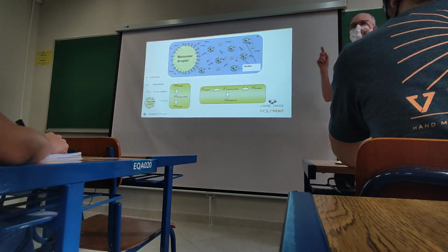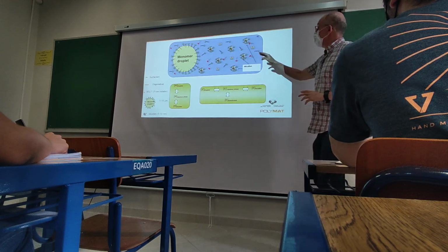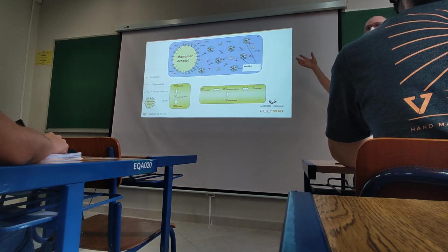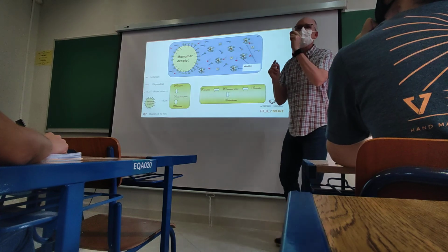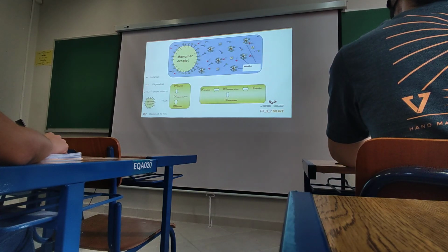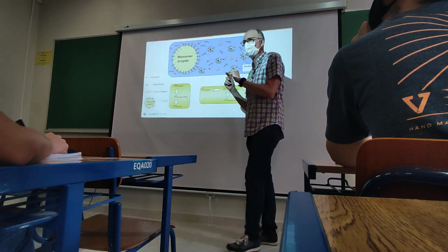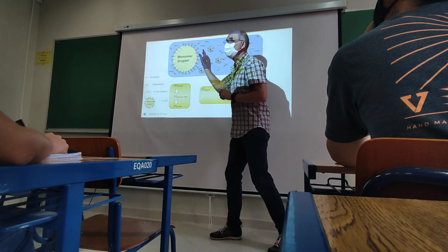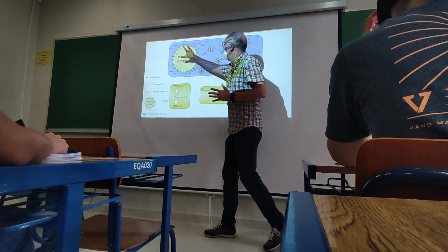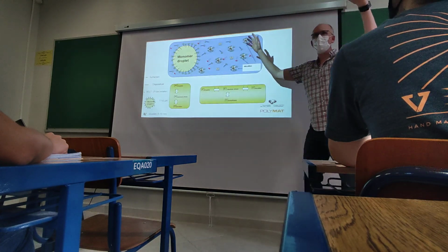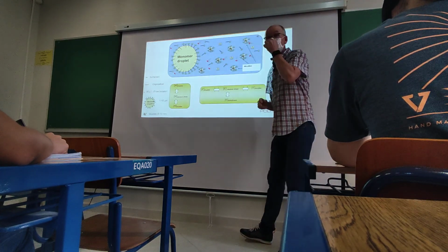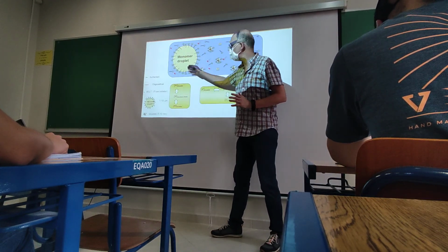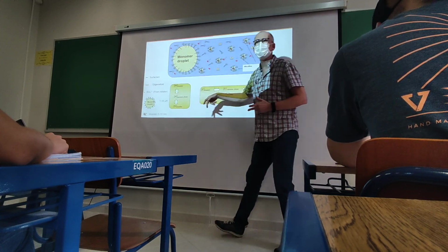The monomer, and this is something that I haven't mentioned so far, the monomer in emulsion polymerization is the oil phase. Okay? The monomer should be sparingly soluble in water. It needs to have a certain solubility in water. So this means that we will have monomer solubilized also in water, but the main monomer will be as big droplets. Okay? And some monomer will be also in the micelles.